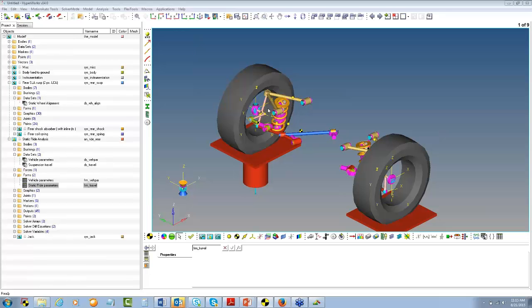Tell me the effect of using a negative camber in front tires. What is the difference between roll center and instantaneous center? No, they are not the same. Instantaneous center, although a very generic term, can be defined for any rotating body. It is the point about which you can assume pure rotation of the complete body. In terms of wheel, we generally call it instantaneous center. When we are talking about the chassis, the point about which it is doing a pure roll is called roll center. So they are a little different.